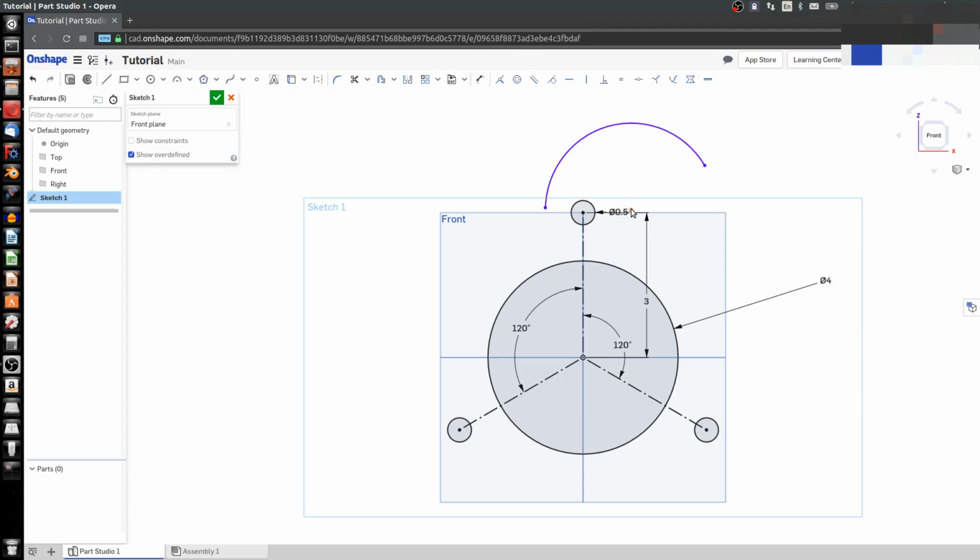And so to get this center in with the center of this circle, I certainly can highlight this center and use my coincident. But to use concentric, I simply highlight the arc and the circle and choose concentric. And notice now, no matter what I do with this sketch, they will always share the same center. So I can use coincident or concentric, both will work.